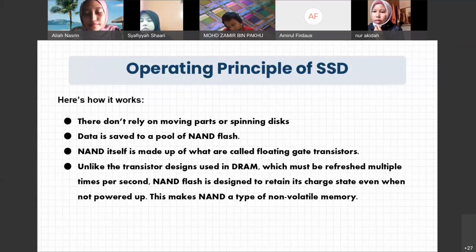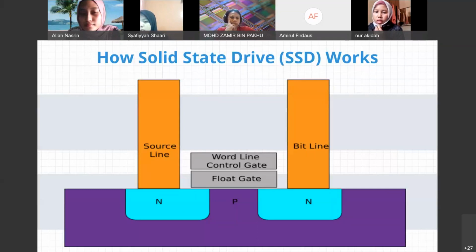The gate contact is made of a highly conducting material separated from the semiconductor by an insulator. By applying a suitable potential difference on the gate terminal, charge can be drawn from the source, and as a result, the barrier is removed, allowing electrons to flow from the source to the drain. Now the transistor behaves as a switch turned on. When the voltage on the gate terminal is removed, the charge movement stops and hence the switch is turned off.